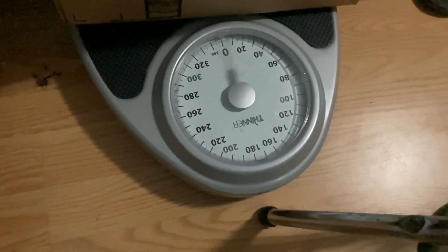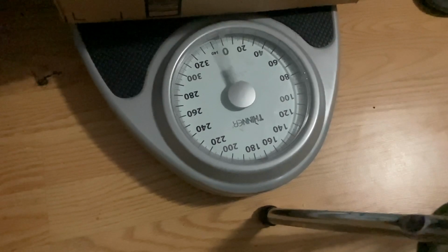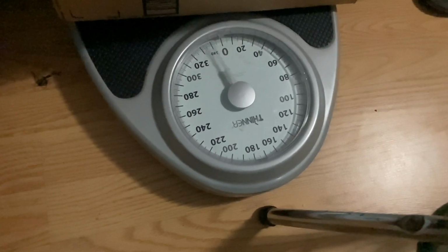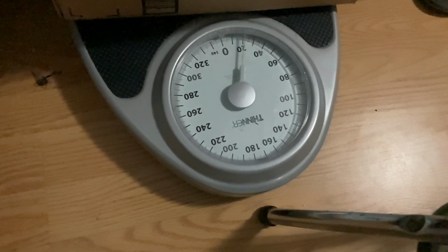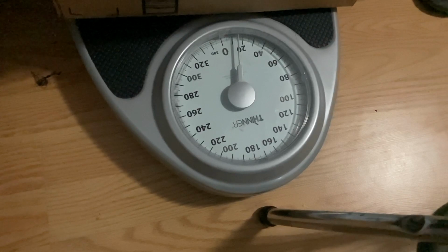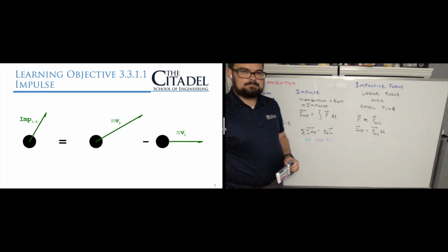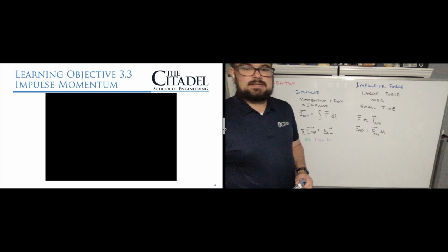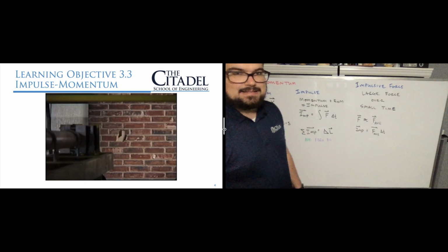And so when we think about this, what we've seen is that in the rigid case, it is catching the load very quickly and getting about 190 pounds of force to bring it to a stop. But in this second case with this pillow here, this cushion, it's increasing the time of that initial hit and resulting in a lower force of around 140 pounds. And so about a 50-pound decrease. Keep in mind, this is a 15-pound medicine ball that's generating that much force. Another example we could talk about is debris impact.